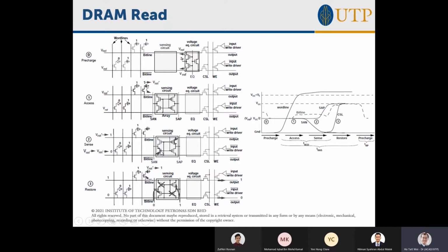And then when this transistor turns on, this bit line is rapidly going to discharge to logic 0. That's why the SAN line will discharge to logic 0, because there is a line connected here that is going to rapidly discharge the bit line. And when this bit line is discharged to logic 0, this PMOS will turn on.